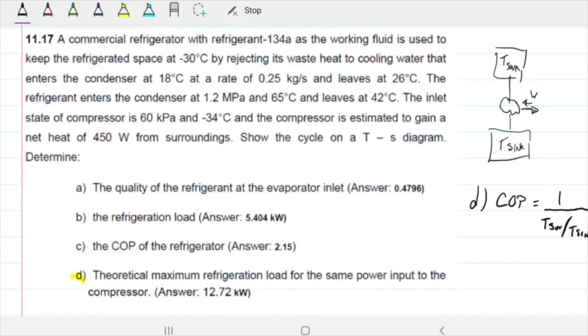Okay, so before we do anything else, we can calculate the maximum coefficient of performance that this system could have. And notice that this has nothing to do with this guy here in the middle, right? It's only related to these two extremes here, which are our sink and our source. In our case, the source that's able to get heat out of the system is this 18 Celsius. That's the water that's entering the system and being able to carry away this energy.